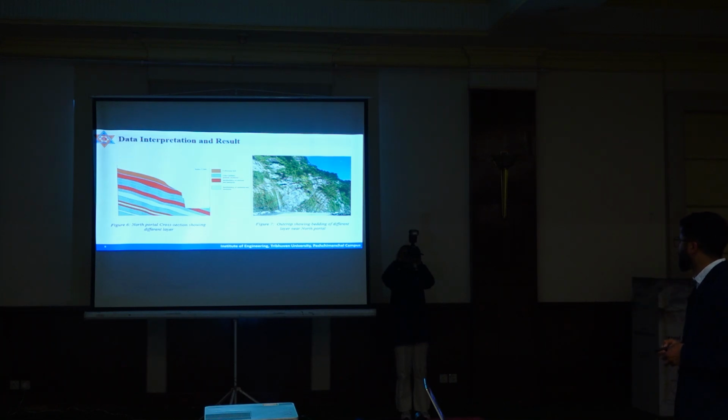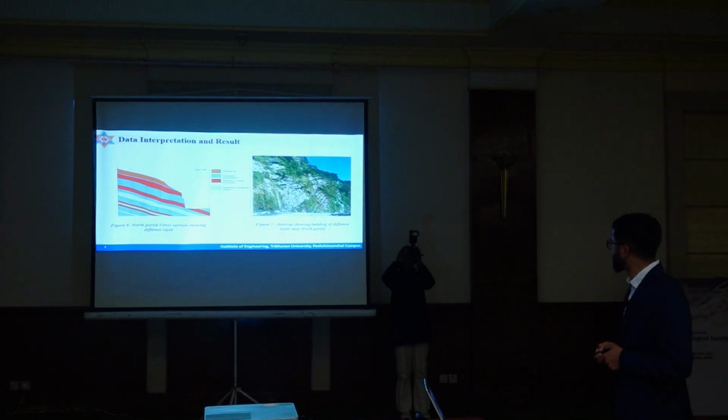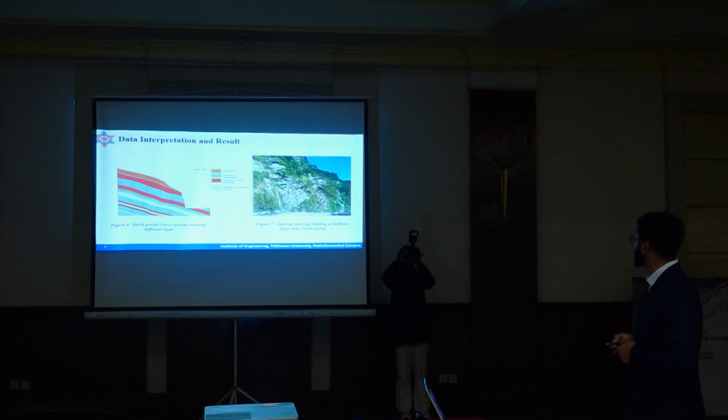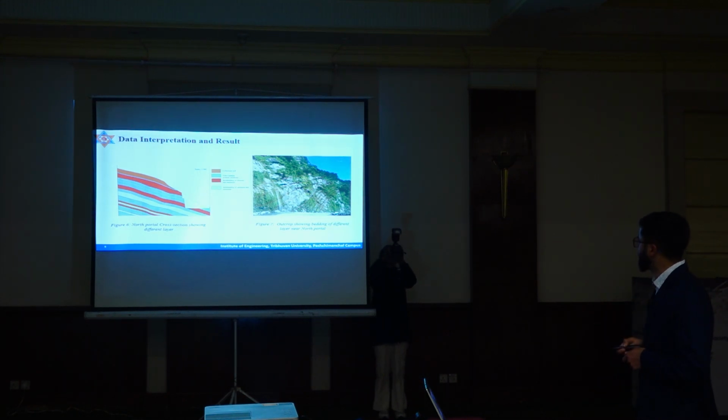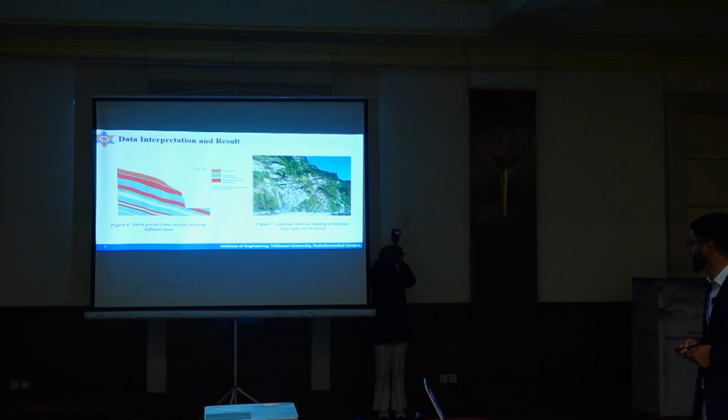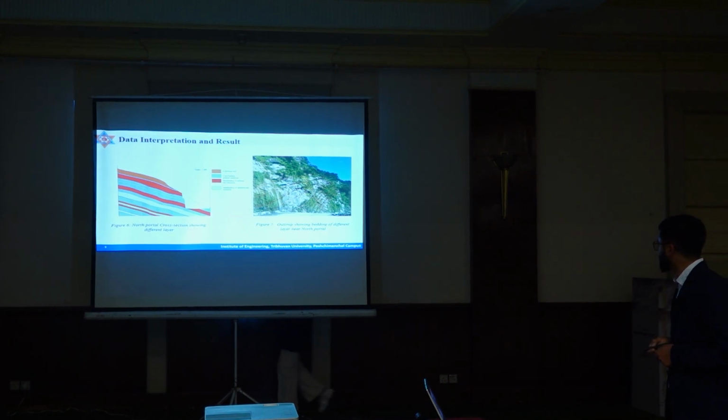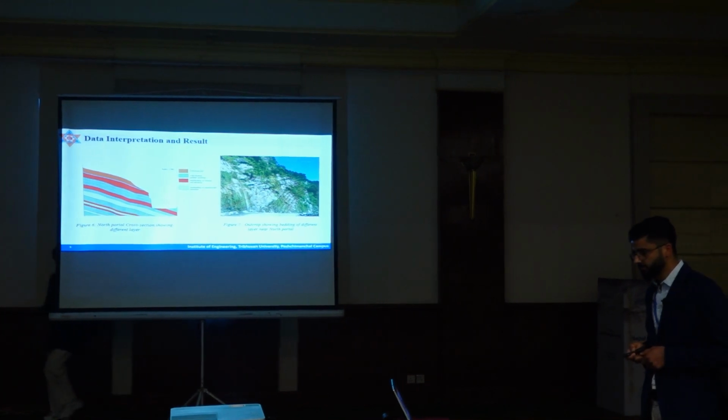This is the nearby sectional view of the south portal, with colluvial soil at the top, fine to medium grade sandstone, interbedded sandstone and mudstone, and interbedded siltstone and mudstone, and the repetition of sequence layers that we can see in the figure. This is the north portal cross section showing different layers. Similarly, colluvial soil at the top, medium grade sandstone, interbedding of sandstone and mudstone, and repetition of layers that we can see. And this is the outcrop showing bedding of different layers near the north portal.